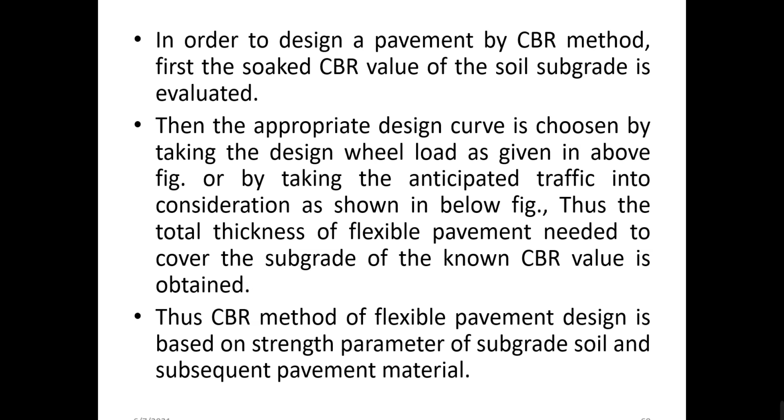If you keep the soil mass for 4 days in the water, and then represent the CBR in terms of percentage after soaking the soil in the water for 4 days, if you test that particular soil mass for CBR determination, then it will be called the soaked CBR value. Obviously, the soaked CBR value will be lesser compared to the unsoaked value.